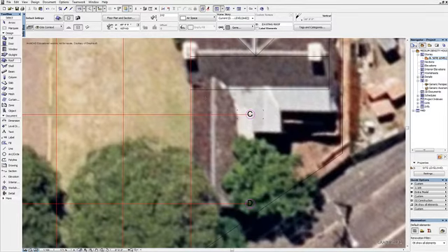So what we're going to do is draw the pitching line here, because this indicates the base of this roof plane. Because we've made the roof intersect at this grid line, we're going to draw a pitching line from here to here. This indicates the base of our roof shape. Now we're going to click to the right of this pitching line to indicate that the roof plane is going to rise in this direction towards the ridge. So I'm going to click with my left mouse button.